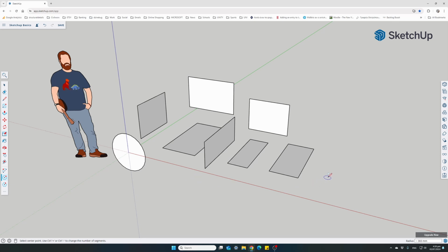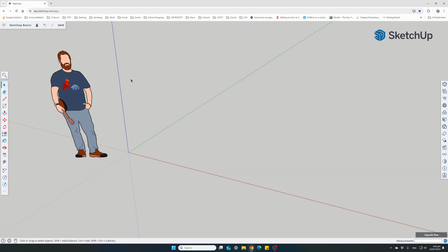Let's do another circle flat on the ground perpendicular to the blue axis. Click on the center and with your mouse, without holding the key down, select the appropriate radius or have it snap onto another object. Let's erase everything we did, clean up the area, and let's do a rectangle. And this time I will show you how to select specific width and depth of the rectangle, without using the mouse, but with using actual dimensions.